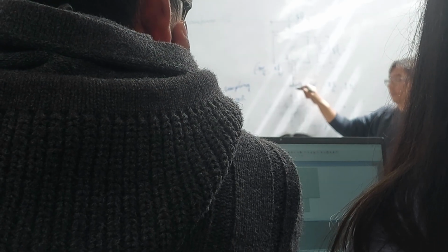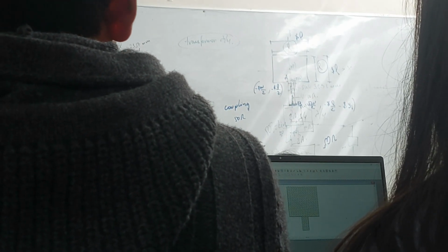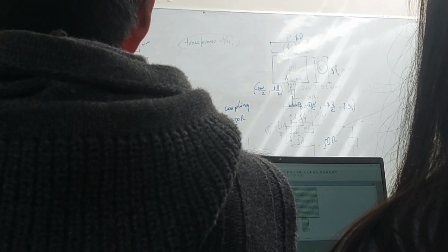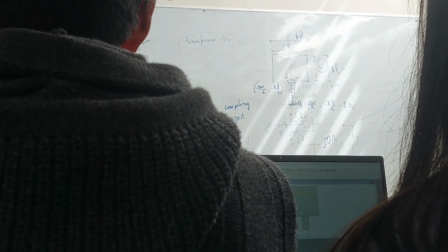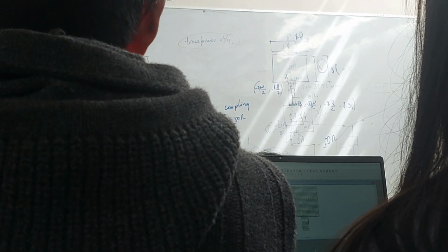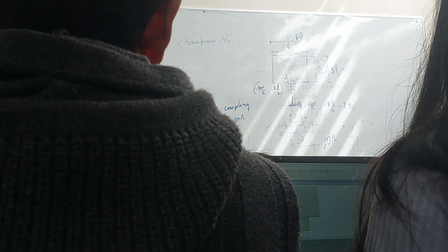Now we need to put here the port, because in this port we need to search for the input impedance. Once we put the port, remember that we put the port selecting this icon, we select the face, we select this, and we go there.